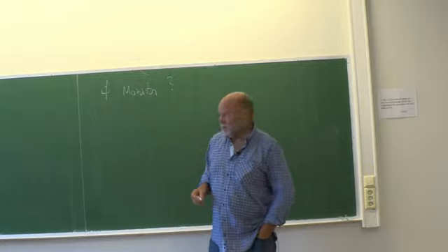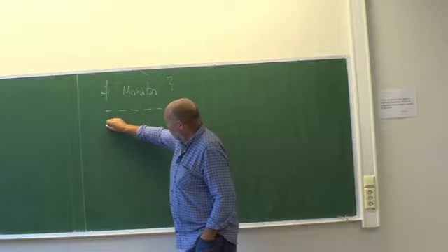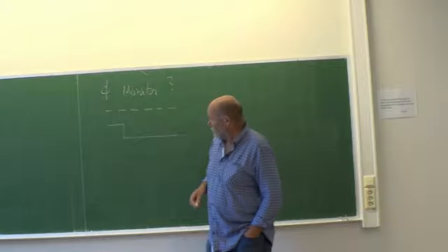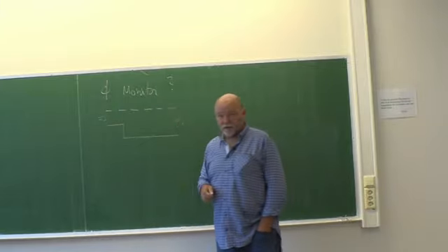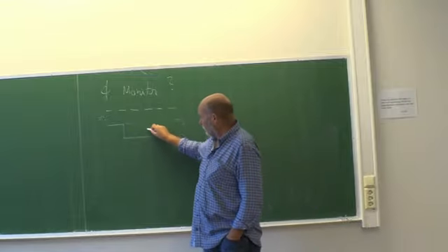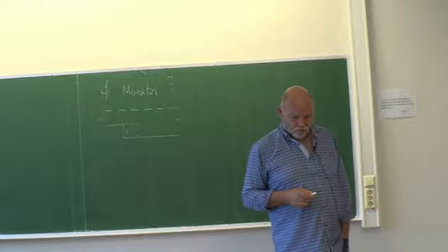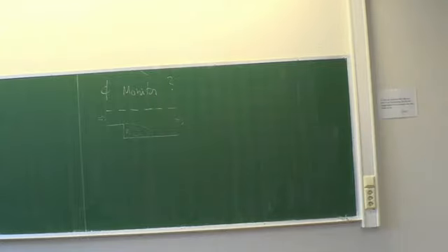Say now, in our case we have a symmetry plane, and then we had a backward facing step, something like that. We send something in here, and we have something going out on the other side. We have this nice vortex here. What is a sensitive monitor for this simulation?